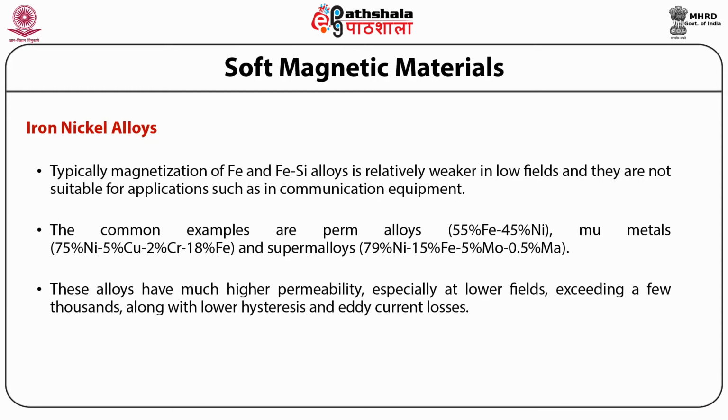These alloys have higher permeability, especially at lower fields, exceeding a few thousand, along with lower hysteresis and eddy current losses.